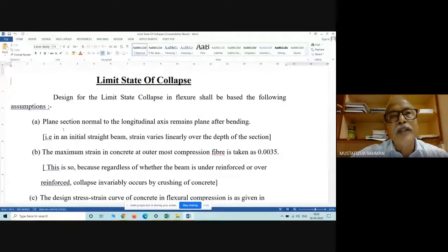From the extreme outer surface there will be maximum tension or compression depending on the surface, and gradually towards the mid depth the compression or elongation decreases. At some point it will be zero. That is the transition point. Immediately after crossing that point, the property of the element at that location changes from tension to compression, or from compression to tension.